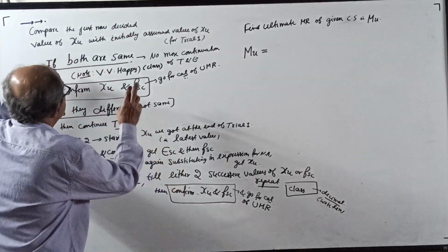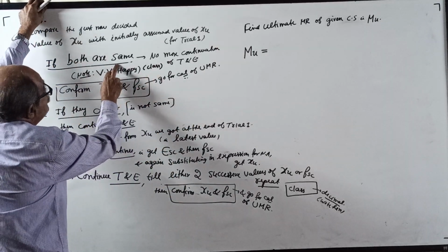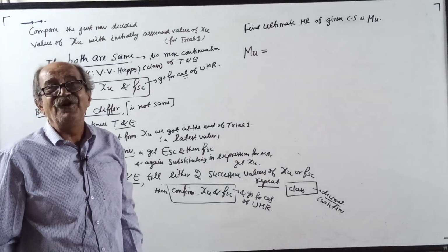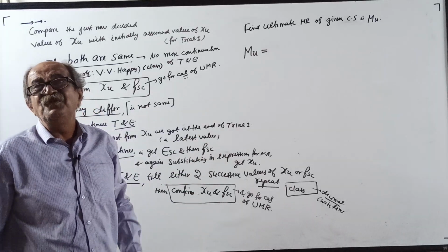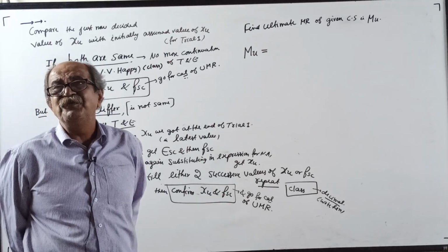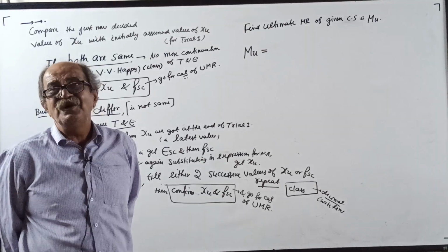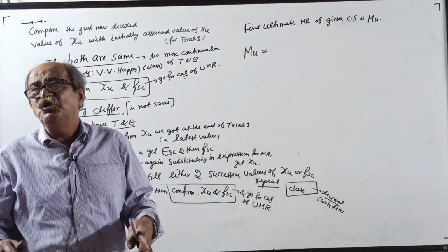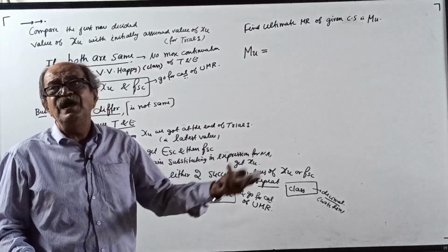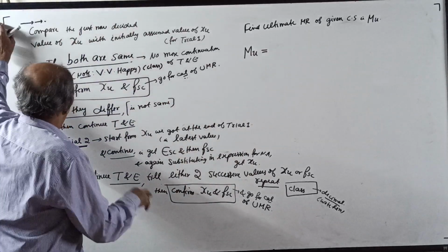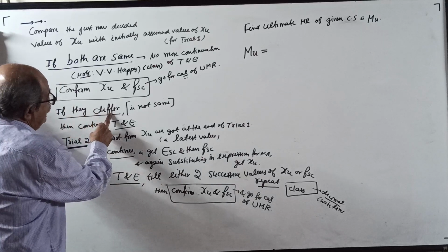Now make a note here, class. This will happen only for an over reinforced section because initially we assume xu equal to xu max. If the section is over reinforced, xu will come more than xu maximum. The more you cancel, you make equal. So initially equal, now also equal. You should be lucky for that one. Okay, leave it.